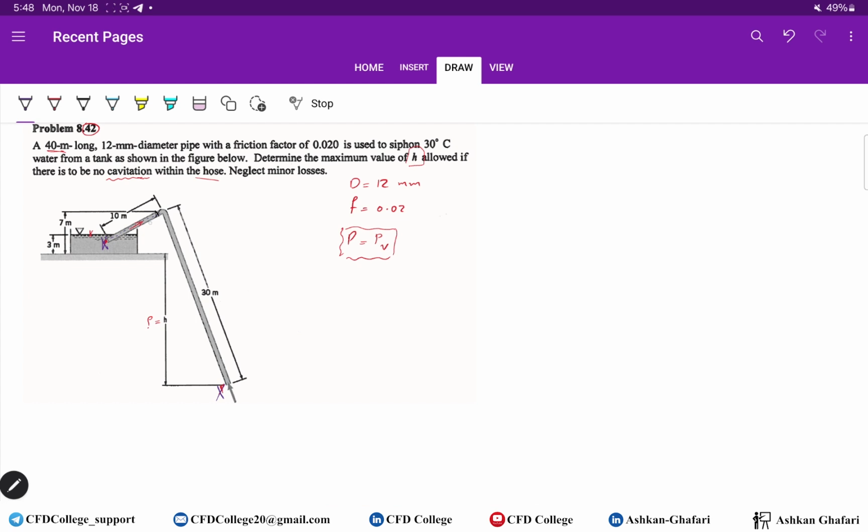The first one is increase in the elevation, and the second one, which is everywhere, is head loss, is friction. So in the second section, when we are moving downward, the water moves downward, we have HL, the friction loss, pressure loss due to friction. But since the elevation is decreasing, the hydrostatic pressure is helping us. Actually, in other words, you don't need to overcome the potential energy.